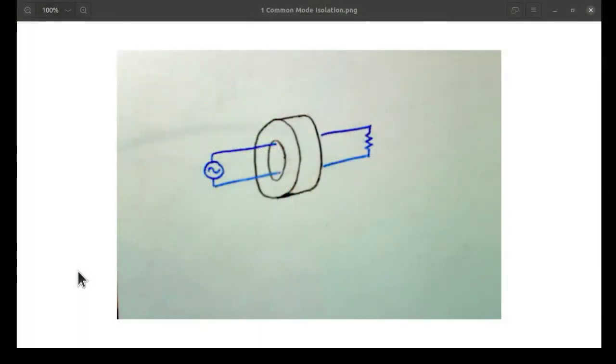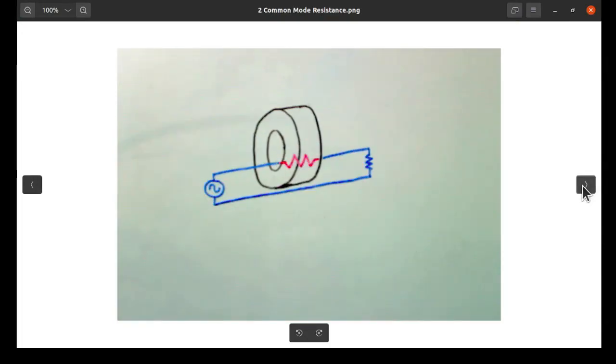And when that drive point, the extension of the transmitter, is up at the antenna, it sees each of the dipole elements and the outer side of that transmission line going back to the transmitter. That is the common mode path, and this is what we see in this representation, where this loss we can see because there's a current going through it, penetrating once, so to speak.